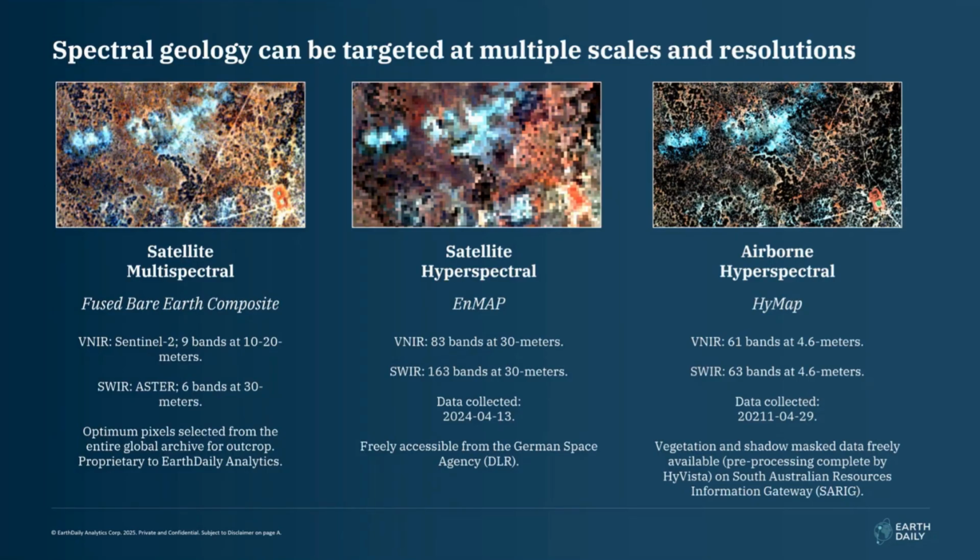It's often challenging in some of these terrains when you've got a lot of cloud in your imagery, shadows, dense vegetation, or it's the wrong time of year where there may have been flooding. So what we've done is found the optimum pixel with the lowest cloud, vegetation, shadow and water, all of these factors that we want to avoid, and produced one global seamless composite.